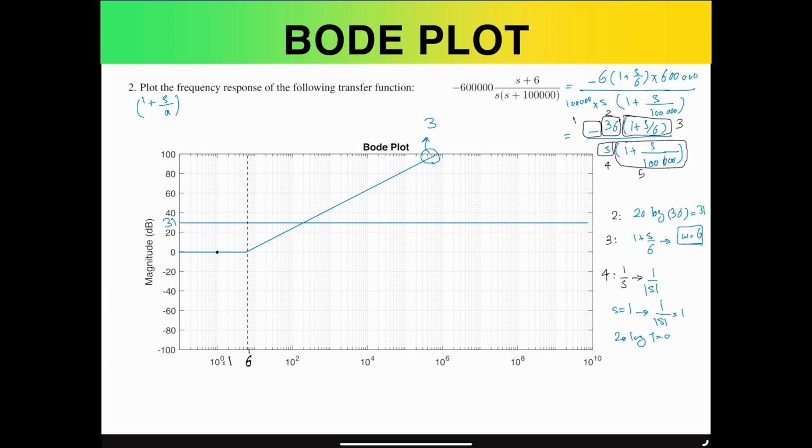So if I try to identify the other points as well, they will be sitting around here. So if I connect all of them together, we'll have a straight line that is passing through all of those lines, and specifically from this frequency of 1 and the amplitude of 0 dB, with the slope of minus 20 dB per decade. So that is how 1 over s is going to be represented. I'm going to just point at that here, and that is 1 over s, or essentially part 4 of this question.